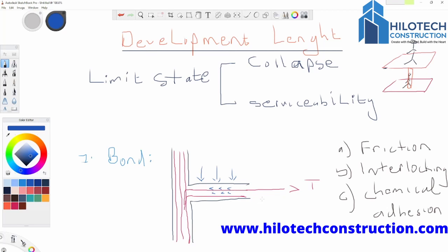So the slab collects the loads from the furniture or from the occupants or from whatever, and sends them to the beams. The beams take that and send it to the pillars. The pillars take that, until it goes down to the foundation where you have the footings, and then the footing takes that and transfers the load safely to the ground. So you are just providing a passage where these loads can continuously be transported. They are being transferred until they finally get to the ground. It is not like any of these components carries the load and holds it. No, it is just a transfer of load.